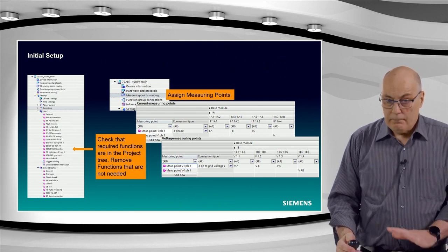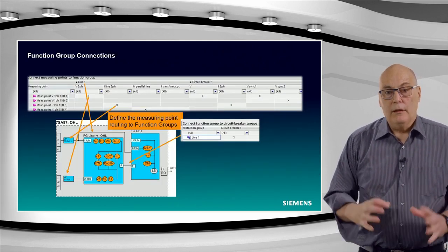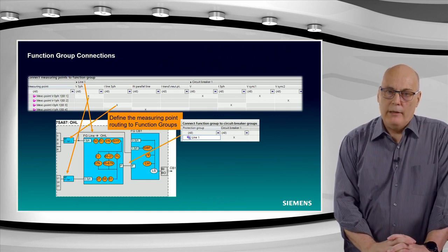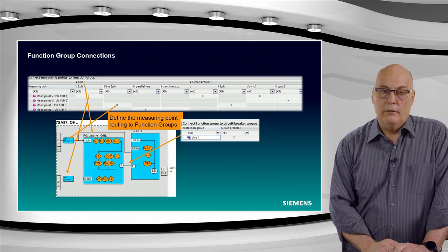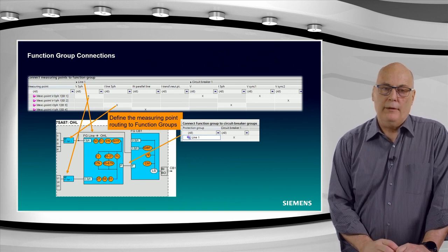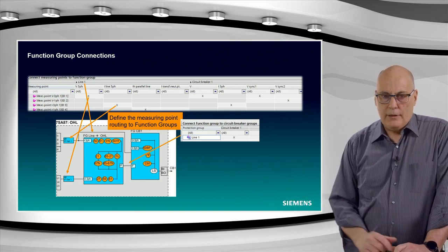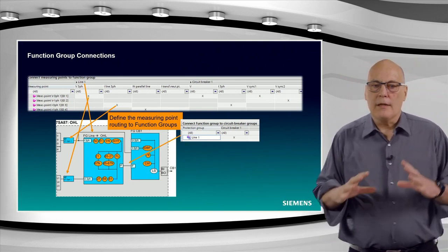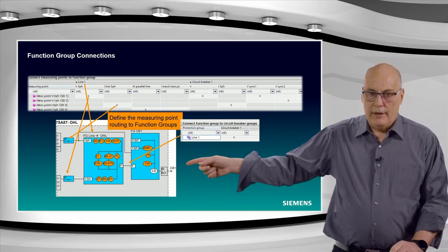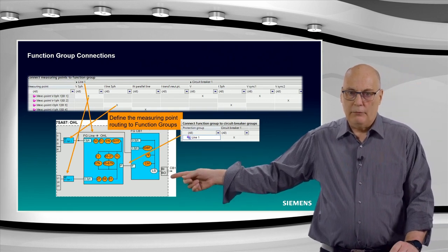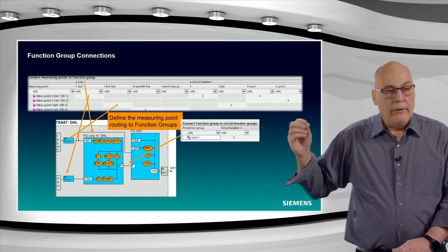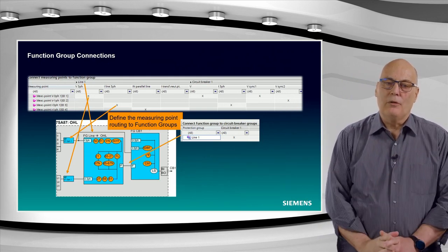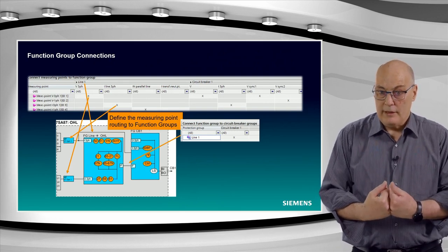All right, that is, I think, the DIGSI configuration as you would do it. This is a graphic representation, maybe easier to explain, to re-emphasize what we just looked at in how you do it in DIGSI. At the bottom, you see this diagram, and you can imagine that the outer gray block is a physical device, and the physical device would have terminals to the outside. Here you can see binary inputs and outputs, for the trip signal to the breaker, maybe the close signal to the breaker, feedbacks for breaker auxiliary status, and so on.